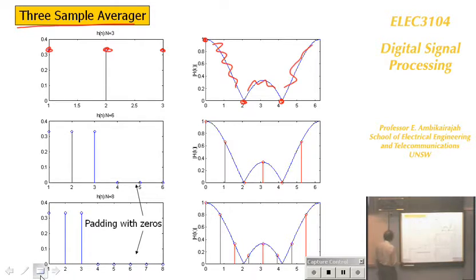So what I did then is, I introduced 3 more zeros to it. I made the number of samples 6 there. And suddenly you see a value has been interpolated between those two by the discrete Fourier transform. You get another sample here, another one, another one. Now you can roughly join. You add further padding with zeros, and the display gets better.